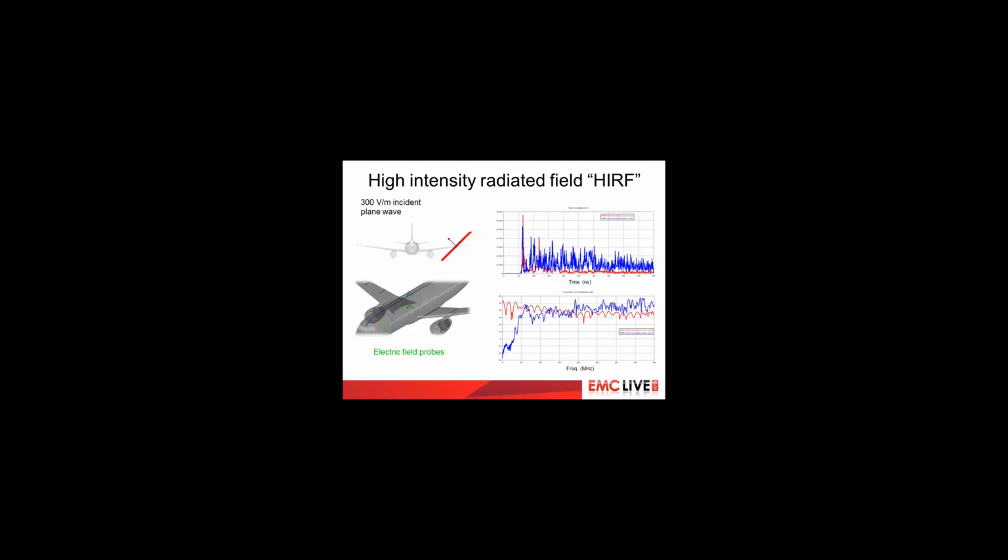Even at low frequencies, there are resonances. And these are the airframe resonances due to the length of the airframe. The internal field, shown in blue, is quite small at low frequencies, below, let's say, 50 megahertz or so. But at high frequencies, it may actually even exceed the external level because of cavity storage and internal resonance effects.